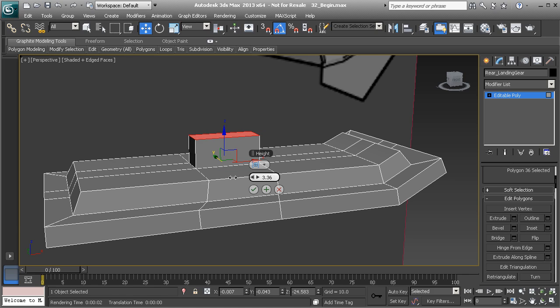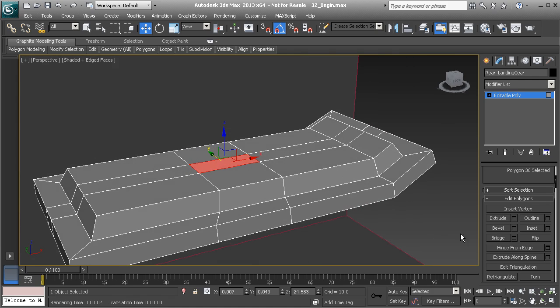And I'm going to extrude this up to about 2. Let's go ahead and type in, let's go to 3. Hit OK. And then I'm going to extrude that again, and we'll keep it at 3 as well. Now I want to show you really quickly how we could create multiple extrusions instead of hitting extrude OK and then hitting extrude again.